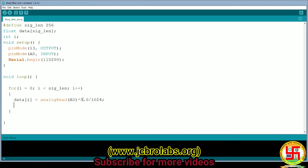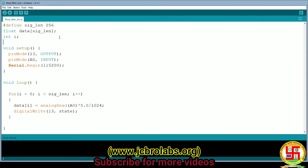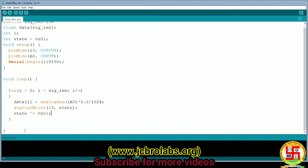Okay, now we will change the digitalWrite pin number 13, right, and we will define it as a state. So here we will define a state variable so that we can toggle it again and again. State equals 0x01, and we'll define it like int. Okay, and let's change it to, yeah, state equals, let's do XOR with this one.